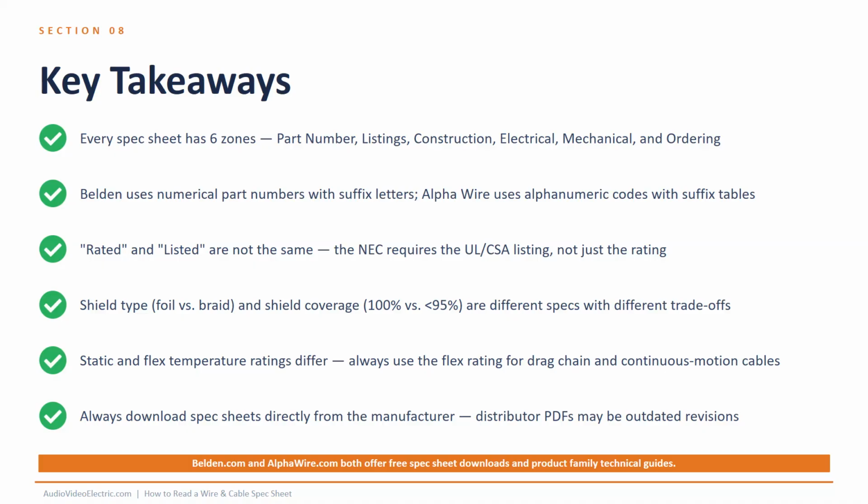Shield type and coverage are different specs with different trade-offs. Always use the flex temperature rating for moving cables. Download spec sheets directly from the manufacturer for the most current revision. Belden.com and AlphaWire.com offer free downloads and technical guides.